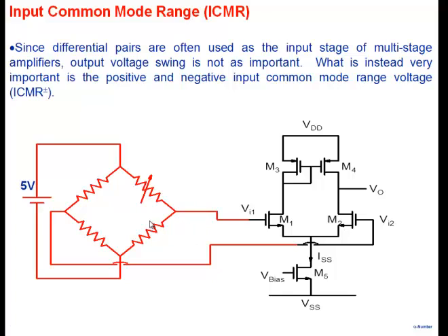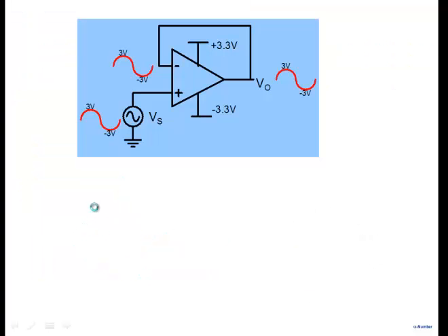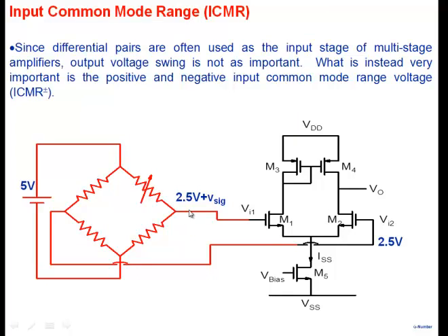So what happens is when you excite this particular bridge, let's say using 5 volts, normally, if all of them are equal resistors, the voltage at this point will be 2.5. The voltage at this point will also be 2.5, basically a voltage divider. Now when you apply a pressure, this resistance changes, and what you get is 2.5 plus some signal voltage here. Signal meaning a voltage which is proportional to the pressure applied, right? But what you note is that on the other arm, you get 2.5. On this arm, you get 2.5 plus the signal.